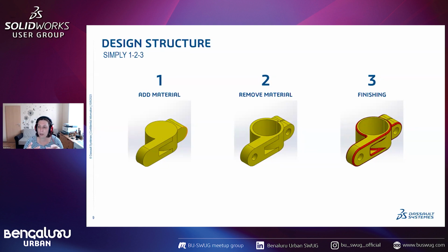I would advise when you have such cutouts, you use the shape without the fillets, and after the cut, you apply the fillets in the corners. But these are technical fillets, the ones you need for the part to be done, because the next steps of your modeling will be dependent on these fillets, and they should be there.